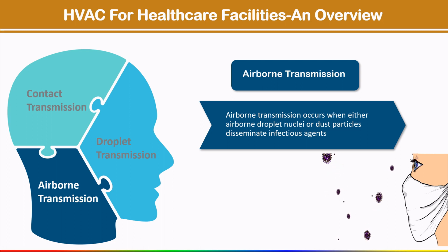Remember, the high velocity with which coughing and sneezing expel droplets from the respiratory tract results in large numbers of bacteria or viruses entering the air in smaller droplets. These droplets rapidly evaporate in the air, leaving a residue typically 5 micrometers or smaller in size. These droplet nuclei settle so slowly that they remain airborne in occupied spaces and circulate on air currents until mechanically removed by the ventilation system. So this is all about droplet nuclei.